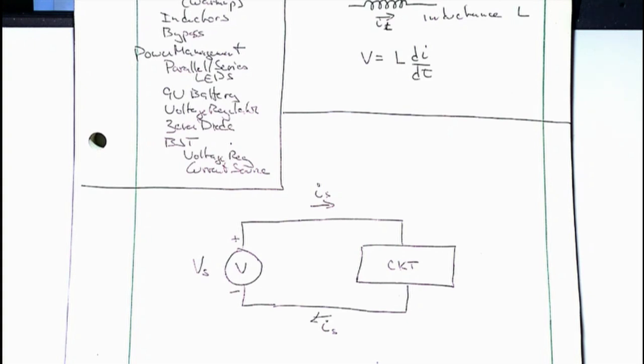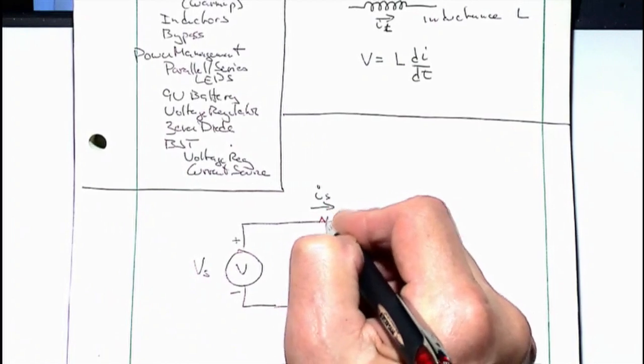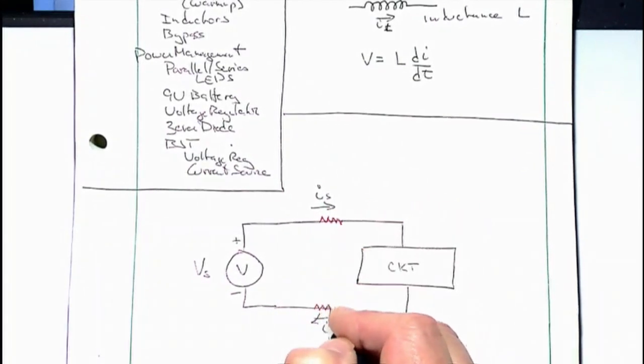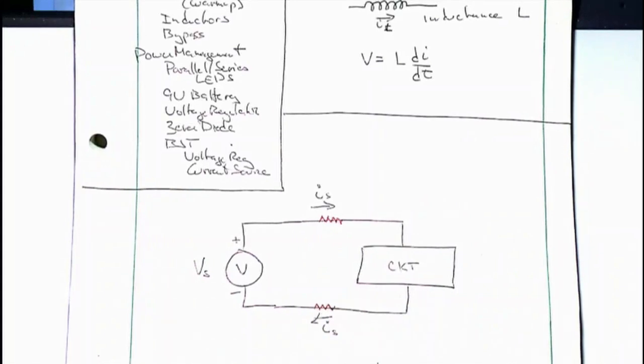Well, that shouldn't be a problem. We're using really good laboratory power supplies. They put out a really fixed voltage. Well, but there is a problem. We're connecting it up with wires, and wires have resistance. I know I've claimed up to now there's zero resistance, but the reality is wires have some small resistance. It might be milliohms. Maybe that's no big deal.